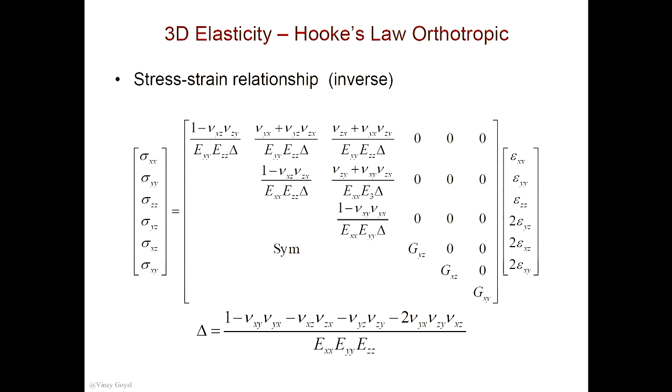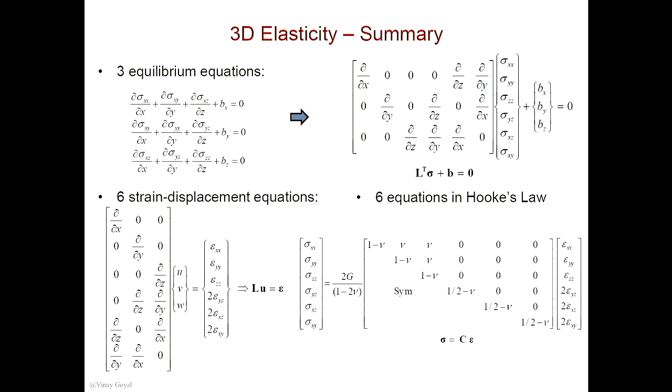The way Abaqus handles this matrix is that you define, or in Nastran it's a MAT9 card, and then in Abaqus, on the materials, you will use engineering constants. And then you can define the 9 different constants for the composite. And that can be done very, very quickly. So this matrix can be defined either for isotropic or composites, no problem. And you can see here it is a 6 by 6. It relates stress to strain.